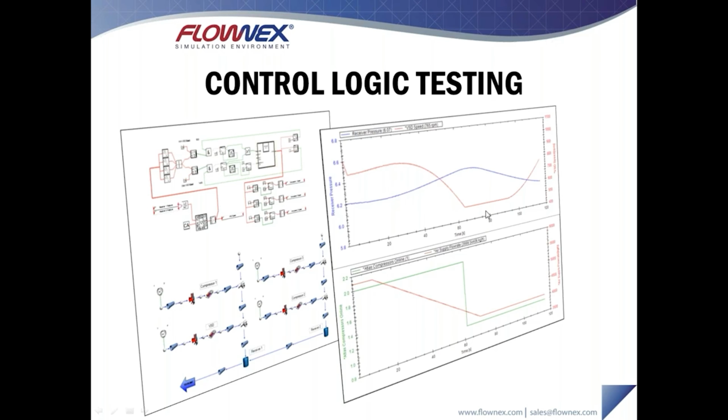reduces. As soon as our variable speed drive reaches its minimum value, the digital control section, through all of these logical operations and comparators and switches, delays, counters, many components all integrated together there, this system itself actually turns off one of the baseload compressors. So that's represented by this green line. It changes from 2 compressors online to 1 compressor online. As soon as that happens, we see the pressure in our tank slowly start to decrease over time.